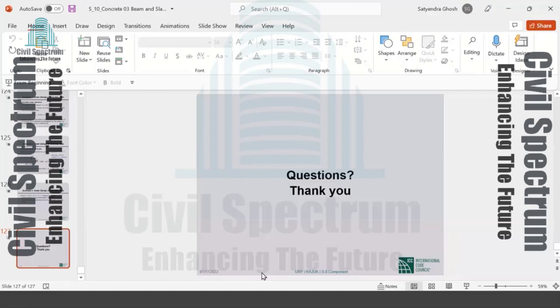If a web shear crack develops in a beam, would FRP wrapping increase its shear capacity? Fiber reinforced polymer, basically. Yeah, the wrapping, I have never seen wrapping used in new construction to boost shear capacity or anything else.